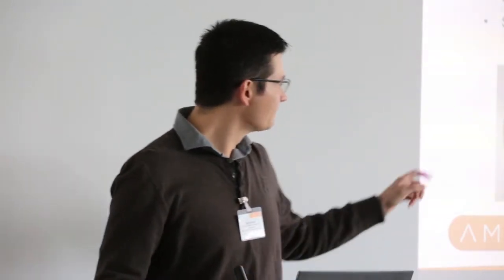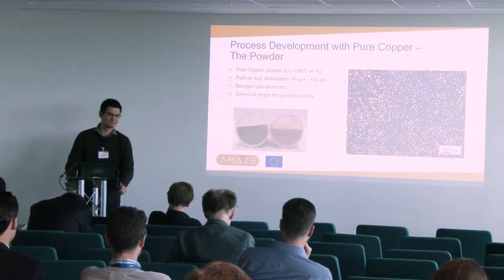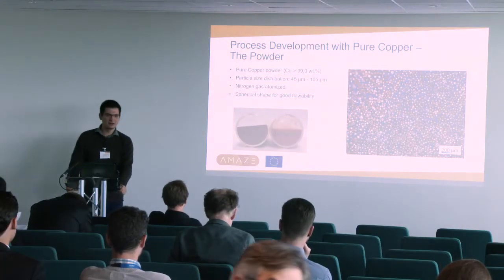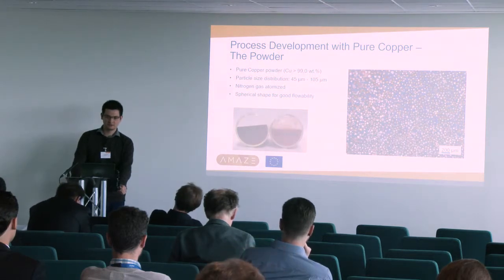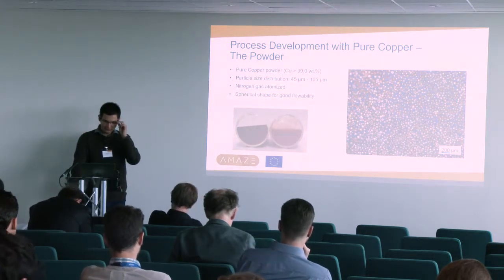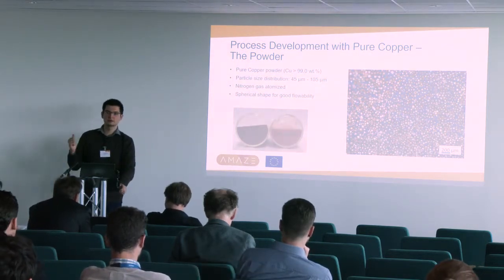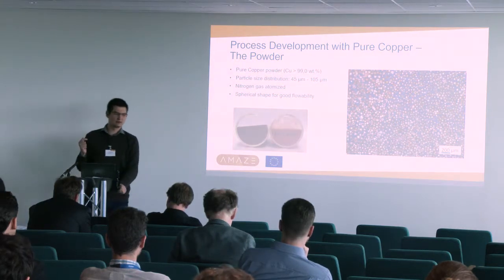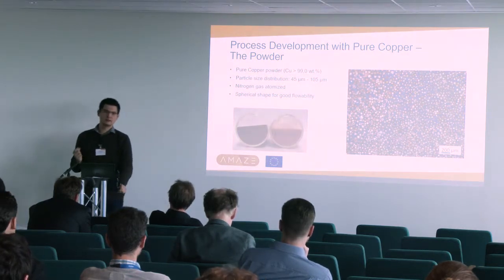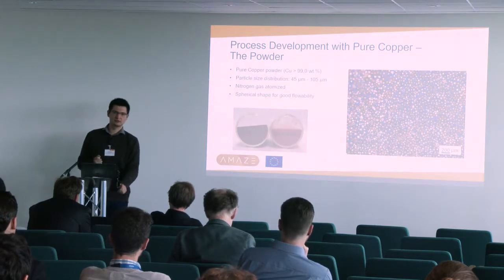On the right side, you can see the color after 3 months. On the left, after 3 years. Basically, if you order a pure copper batch from the same supplier 3 times, you will get 3 different colors. It's very hard to get good powder with really low oxygen levels, and you want them without oxygen, and without phosphorus, because this lowers your thermal conductivity and your electrical conductivity.